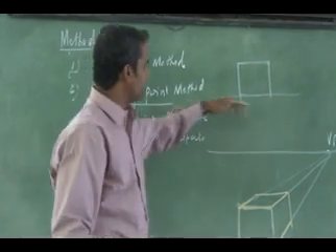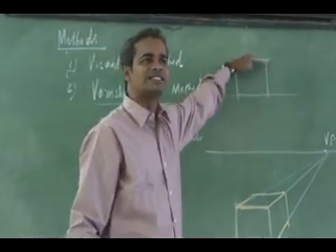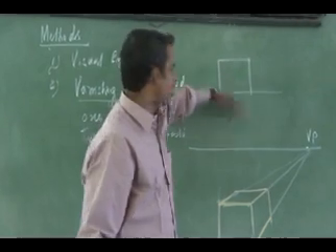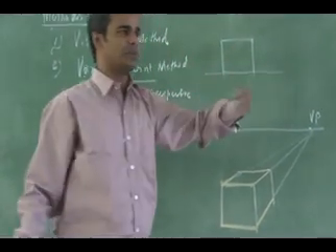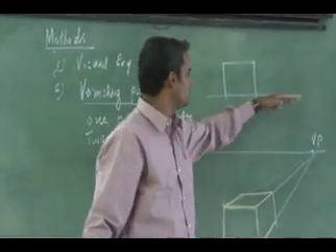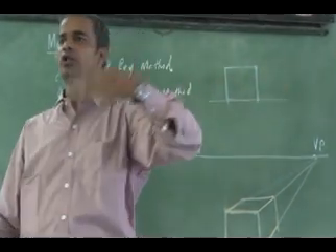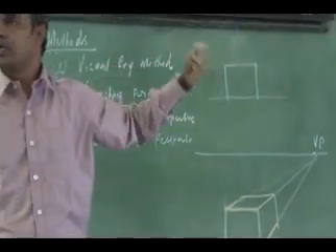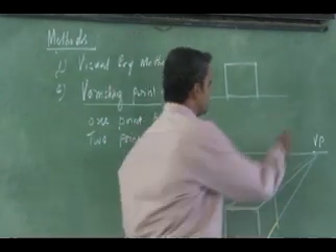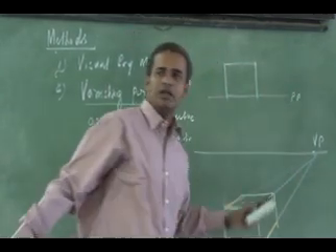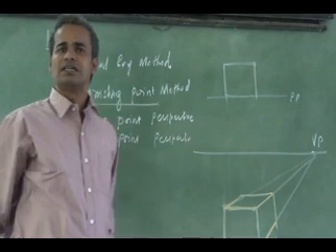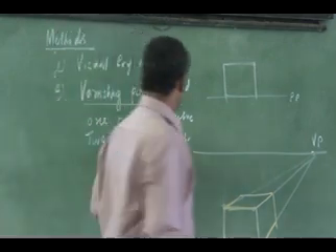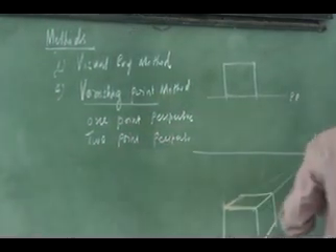Normally, in single point perspective, we go for it if this face of an object is parallel to my picture plane, similar to this setup. The face is parallel now, so this is my picture plane. If it is parallel, I can go for a single point perspective.